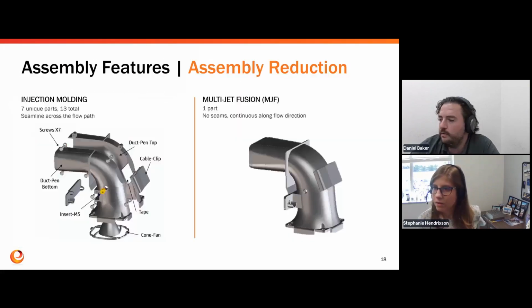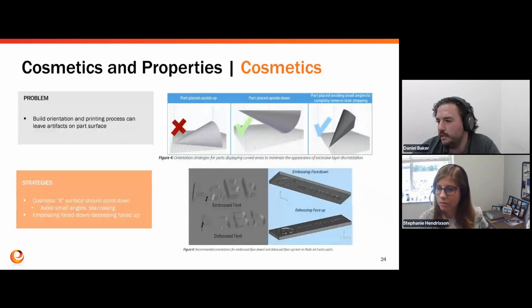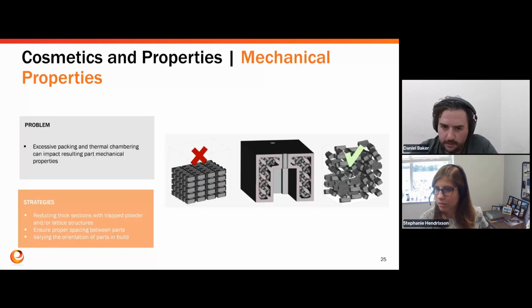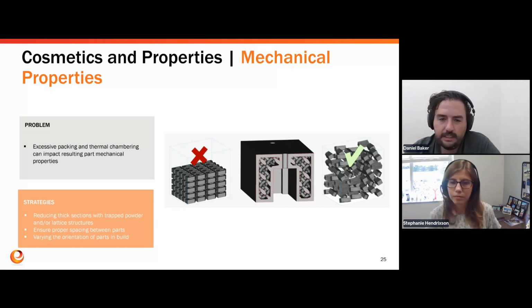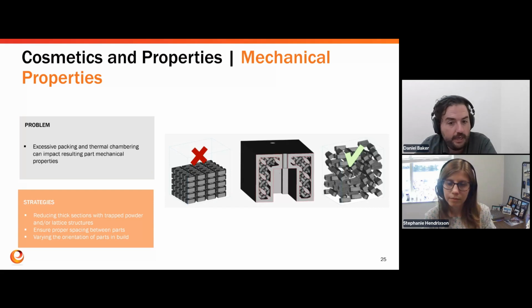Yeah, you have two options. You can print them enclosed or hollow, or you can add a relief. So what I've seen is, say you've got a hollow sphere and there's no way to get the powder out. You can leave the powder on the inside if that's okay. If the part is fine to be dense, it will just be uncured nylon powder.